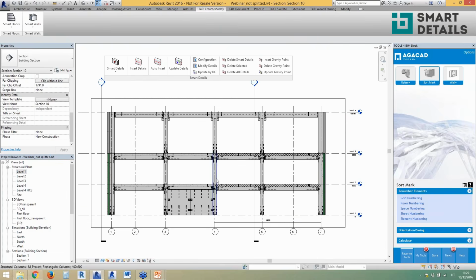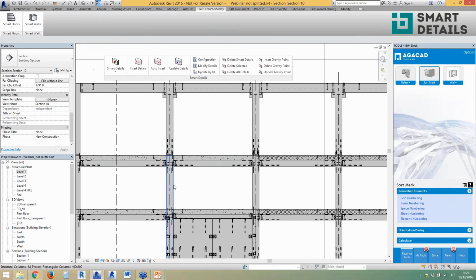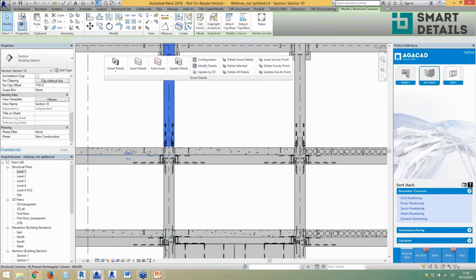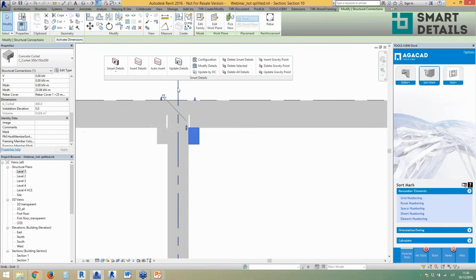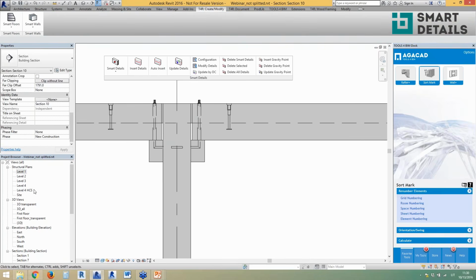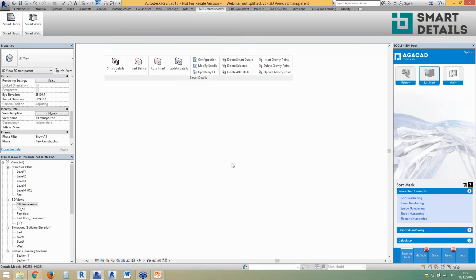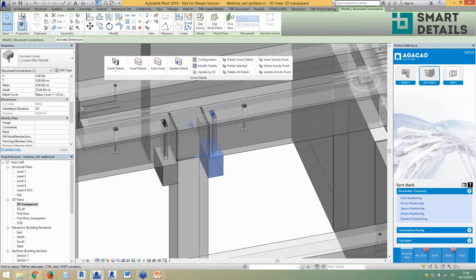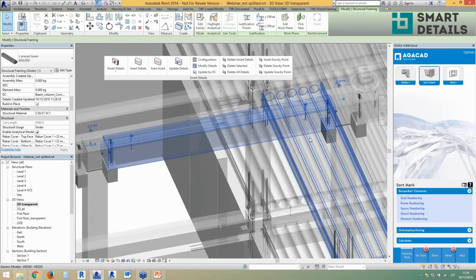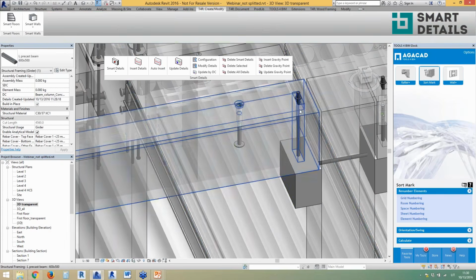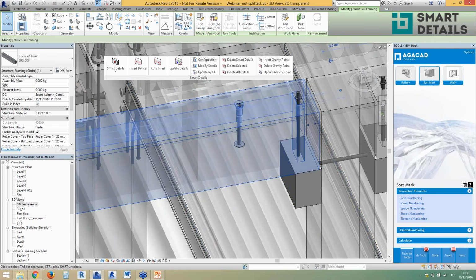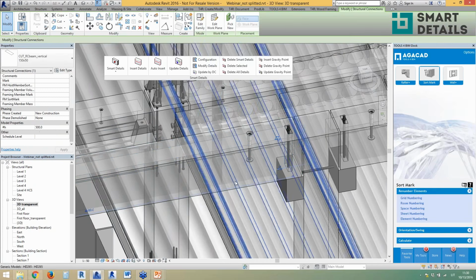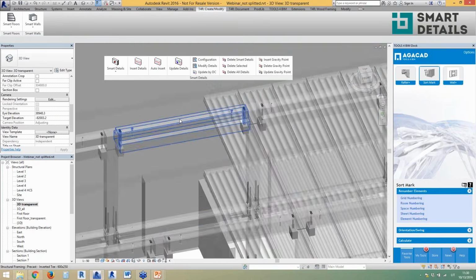So okay, you see different ways that I have this element with steel corbels, and now I have this one with concrete elements, with the bolts. If I go to the 3D view again and see how it looks, now I have concrete, and I have my beam with holes. Again, the hole is adapted to the size of the beam. It takes the H value and cuts through the beam.